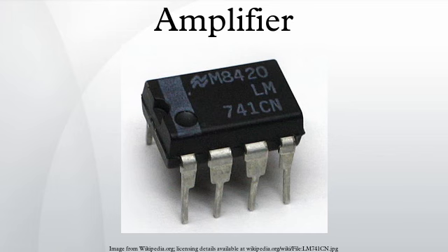Class B. Class B amplifiers only amplify half of the input wave cycle, thus creating a large amount of distortion, but their efficiency is greatly improved and is much better than Class A. Class B amplifiers are also favored in battery-operated devices, such as transistor radios. Class B has a maximum theoretical efficiency of π/4. This is because the amplifying element is switched off altogether half of the time, and so cannot dissipate power.